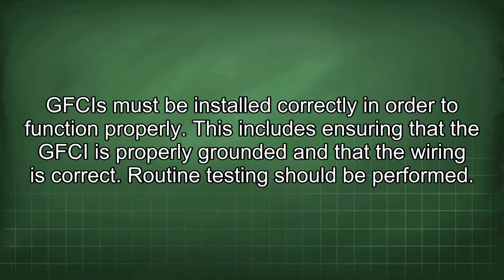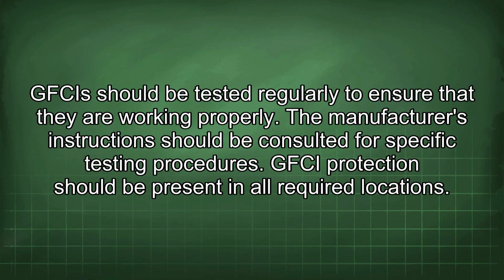Routine testing should be performed. GFCIs should be tested regularly to ensure that they are working properly. The manufacturer's instructions should be consulted for specific testing procedures.